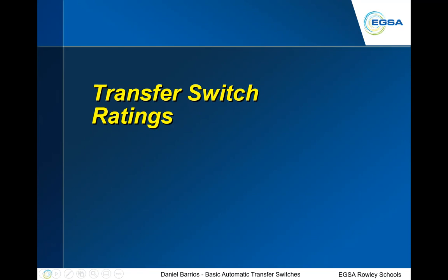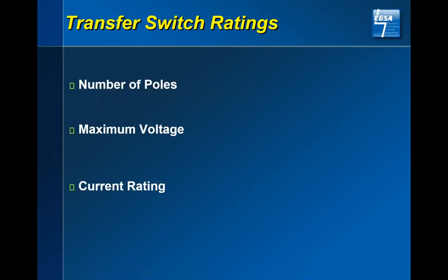All right, so we're back at it here. And we're going to start the deep dive a little bit more into some of the conditions of a transfer switch. As I stated earlier, you need to know the number of poles, whether it's 3-pole, 4-pole, 2-pole. You need to know the voltage. Now, one thing that's neat is one of the manufacturers, I believe it's Eaton, has put out a transfer switch that will identify what the voltage is when you connect it. Some of the manufacturers, such as ASCO, you still need to tell me whether you're operating at 240, 208, because we may have a specific controller that needs to be there.